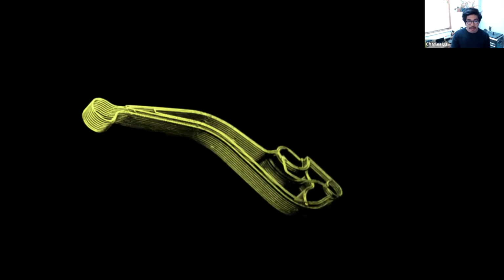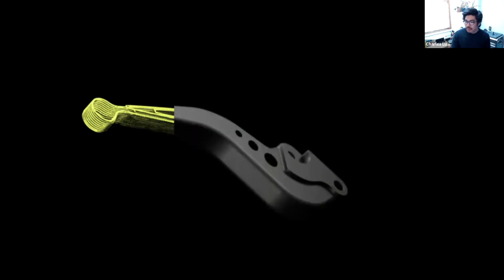And if you've ever done any beam bending theory, or maybe in a statics class in the past, done any sort of analysis on composite materials, putting the strong material on the outer surface is the best way to get the best bang for your buck. So that's the reinforcement, right? And so when we realize that is what's filling up the part, you get a part as a whole which is just a lot stronger than what it could have been if it were filled normally with a chopped fiber polymer.